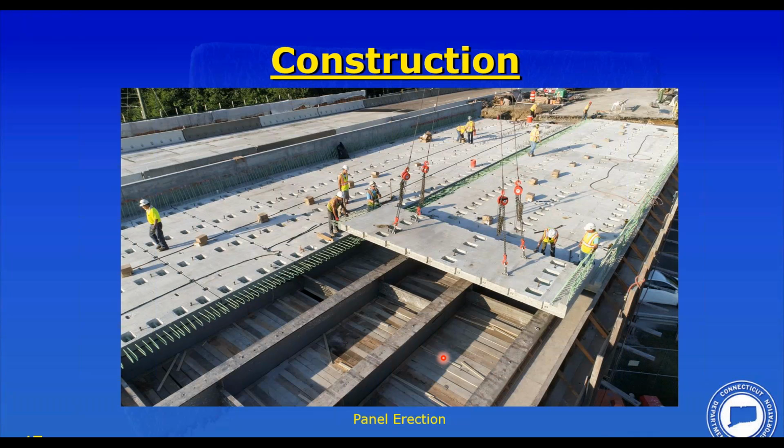But like I said, we look at all forms of ABC when we scope out these projects, and that is changing over time as we get more sophisticated with ABC. This project today might very well be a UHPC joint project, but all options of ABC are considered for each site. We do our structure type studies, and we look at whether or not we want to use SPMTs, modular deck beams, precast decks. There's quite a bit of work that goes into that portion of the decision process, which essentially comes down to a life cycle cost analysis on whether or not we want to paint the steel or replace it with something like weathering steel. That's something we consider in every project.